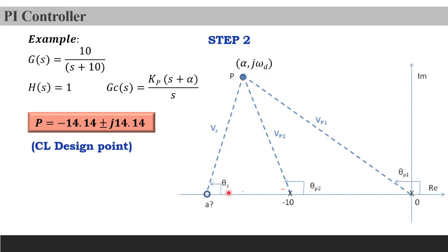So now you want to choose the value of a, or this a you can say, right, or alpha, you can say alpha or a are the same, and this is actually the sigma. And unfortunately the symbols are the same, but I should have changed that. But yeah, this alpha and this a are same, but this is sigma, and you want to choose the value of a in such a way that this root locus should pass through this point.